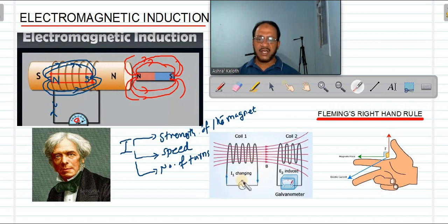So if it is an alternating current, not the current from a battery, the supply current right now in our building is AC. In India it is produced at 50 Hertz frequency, which means the magnet will be rotating 50 times in 1 second. In one half rotation, current will be flowing towards the right, and in the second half towards the left. So in 1 second the direction will change 100 times, so the magnetic field direction will change 100 times. It means there will be continuous change in magnetic field. So if AC is flowing through the primary, there will be a continuous current induced in the secondary.